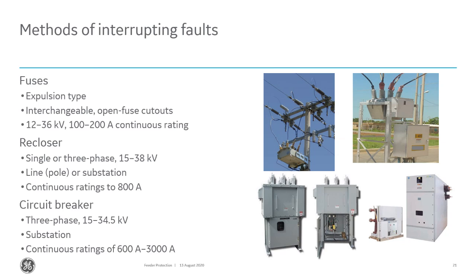Now, if your short circuit is low and your continuous rating is low, there's no reason you could not replace the circuit breaker with a recloser or pad mount reclosers. There's no reason you couldn't. I've seen cases where people are doing that because obviously it's cheaper, more economical, easier to install, easier to replace. So there are some advantages of doing that. But for the most cases, you'll see circuit breakers because of the capabilities that we need, specifically the continuous rating and the short circuit interrupting rating.